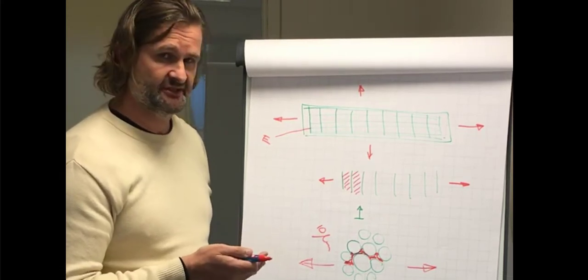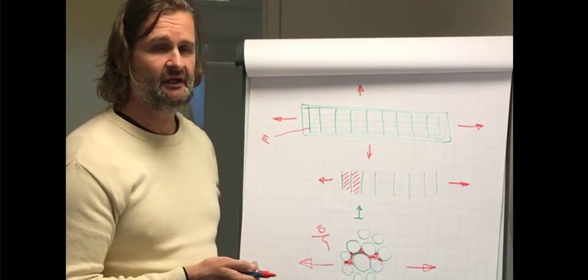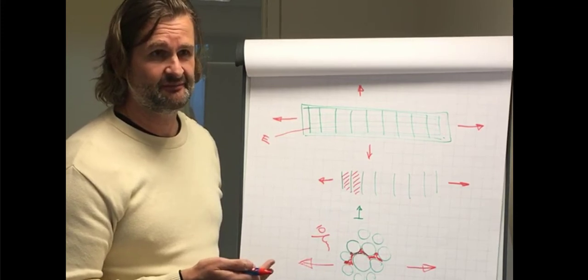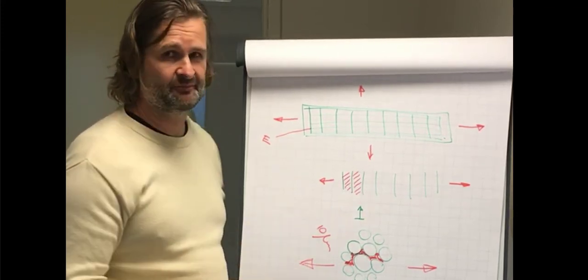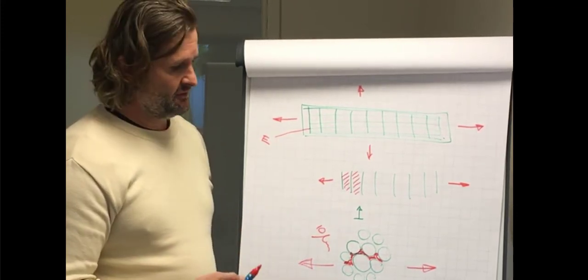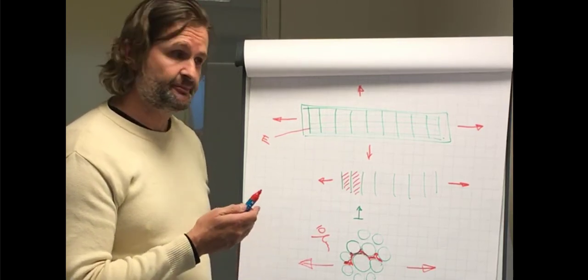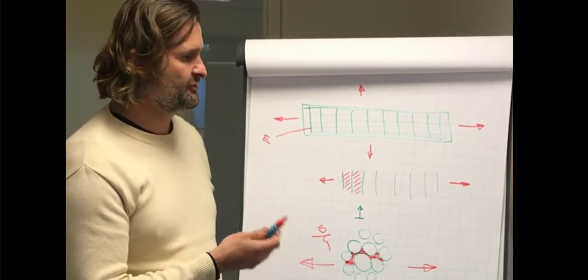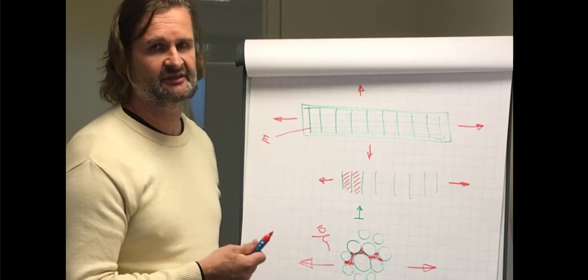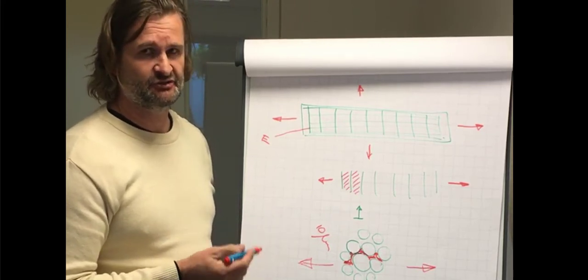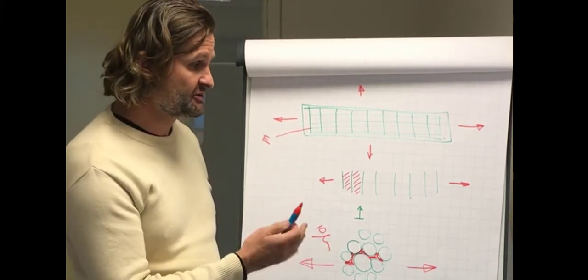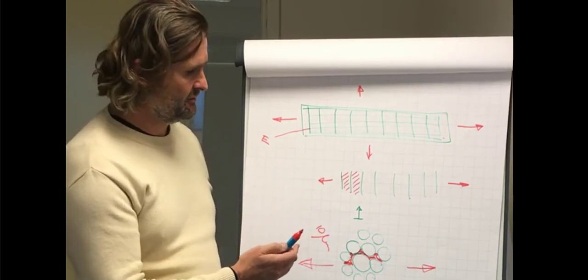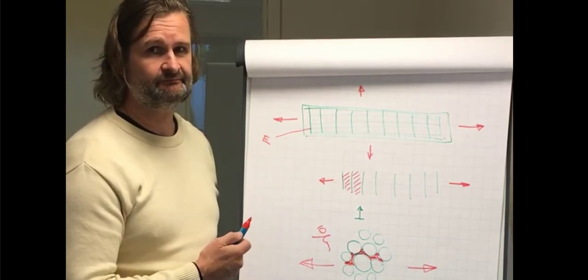Unfortunately, carbon fiber is 20 euros per kilo and glass fiber is €1.50 per kilo. So this is a big compromise that we're making. Nonetheless, for exceptional programs, for projects that really have a specific need, we could always consider using carbon fiber, which will obviously push the boundaries of microcracking. Thank you.